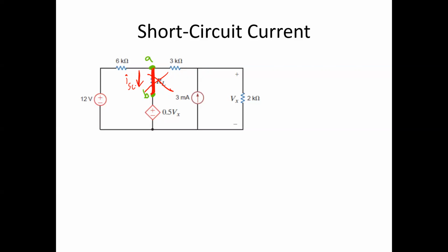And again, this is now the circuit that we have to solve. And again, you can go about doing this with any method that you see fit. In this case, I think I again used a node voltage method. One thing that you can do if you think it simplifies things for you is you can apply a source transformation on the right side of the circuit.